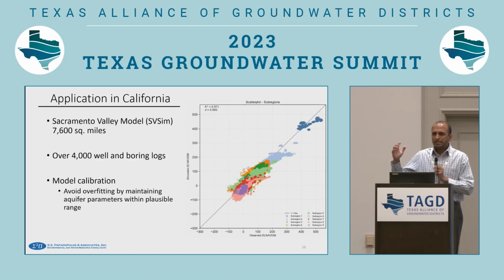But once we did that, that gave us a lot of control on how much water is flowing through the system, one, and how much storage capacity the aquifer has. So those two are important and often underrated or undervalued and underutilized information.